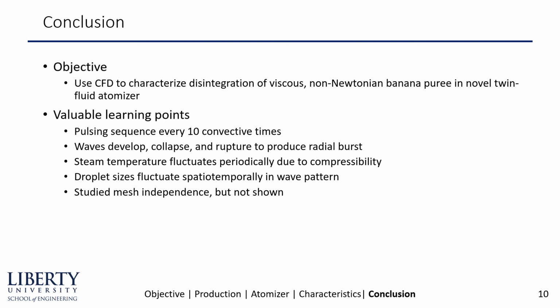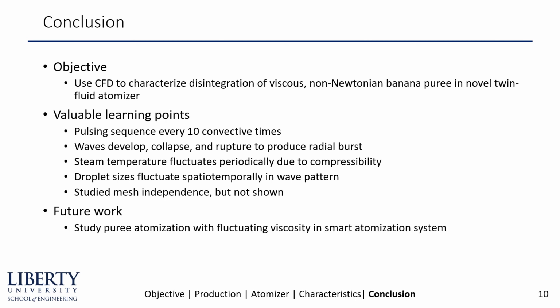Steam temperature fluctuates periodically due to compressibility, and droplet sizes fluctuate spatiotemporally in a wave pattern. We also study mesh independence, but it's not shown here for sake of time. In the future, we'd like to study atomization with fluctuating viscosity in a smart atomization system that we're developing.